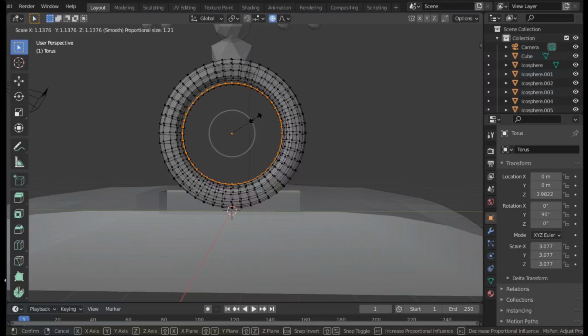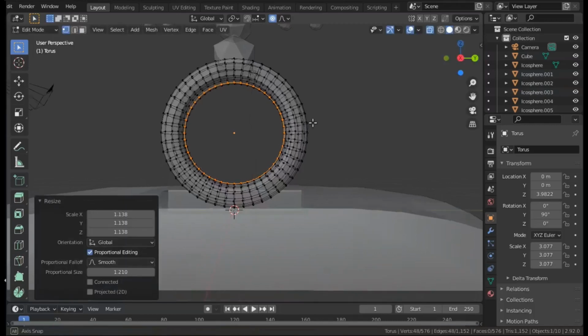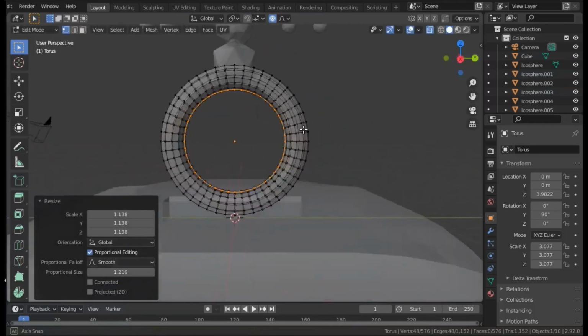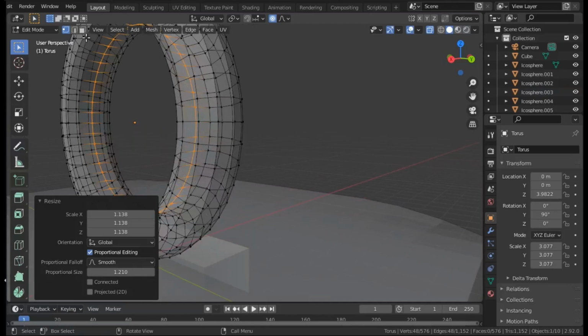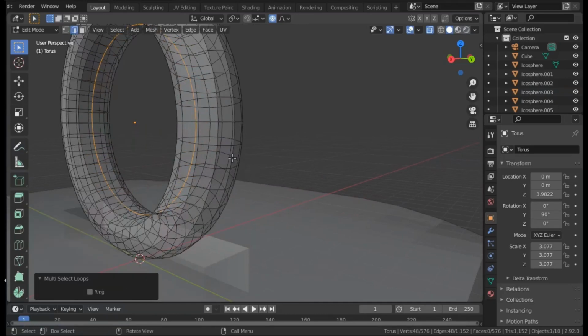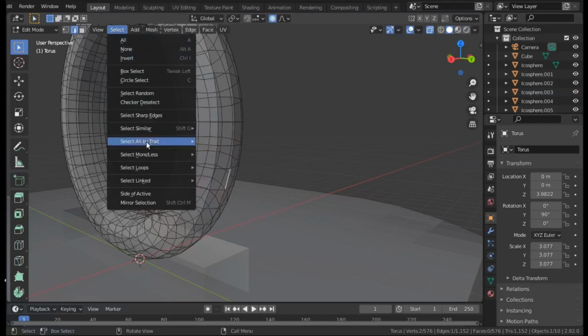So now, without using the shortcut, the edge loop selection is rather convoluted. We have to use select loops, edge loop, but you have to select one edge first, and we'll see that actually using Shift, Alt and clicking on an edge is much more efficient.